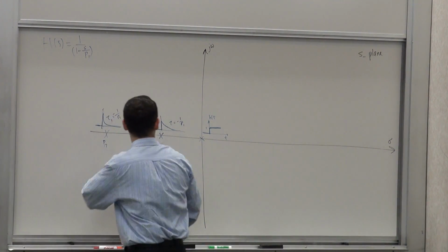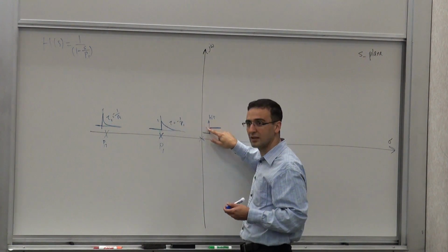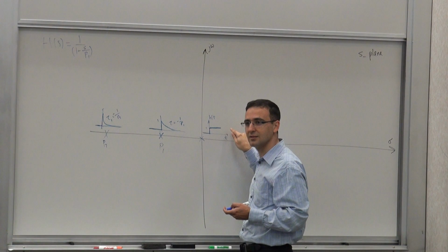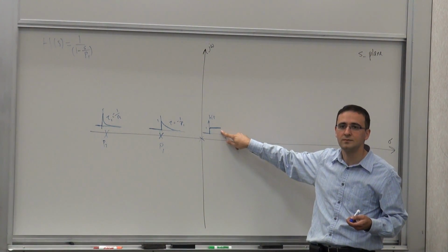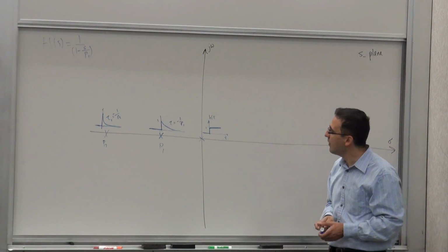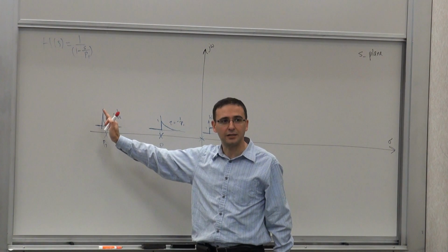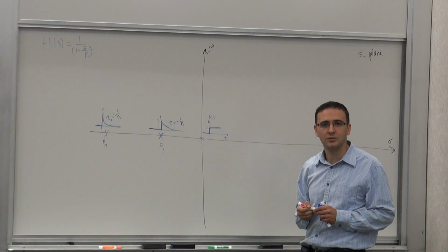In the limit going the other way, the time constant becomes longer and longer, basically infinitely long. So it becomes constant: a time constant of infinity, a pole frequency of 0. So this is our point. These are poles with negative real value. So what if I had a positive real value? What would I get?